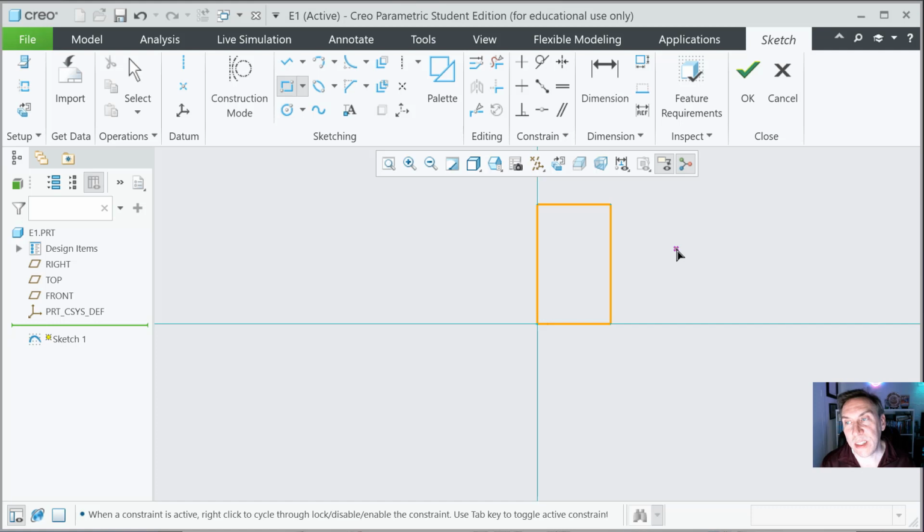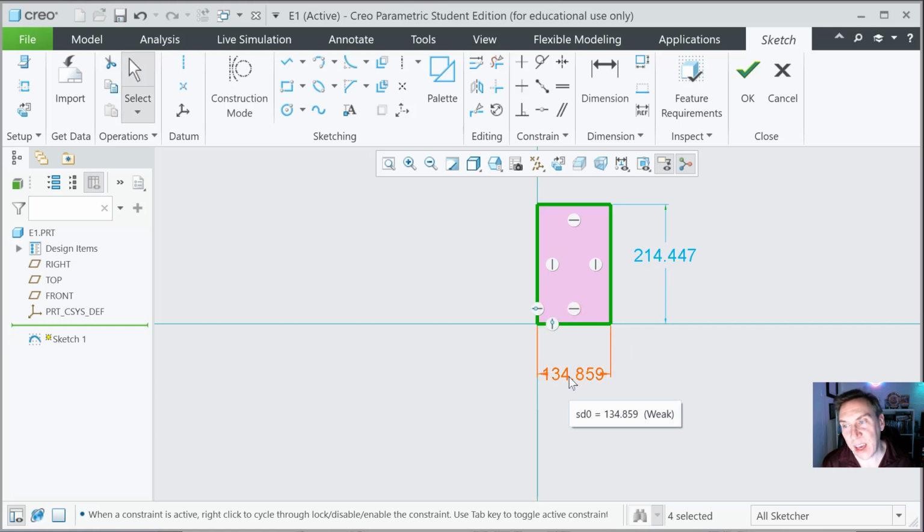Now here's the interesting thing. It automatically dimensions for us. Watch this. On your wheel, click on it one time like it's a button. Don't scroll it, and release. The dimensions should appear. Now you get these really big dimensions, and we're going to adjust that. So double click on this one at the bottom, and you can see all the decimal places that goes up to. Very high precision technology.